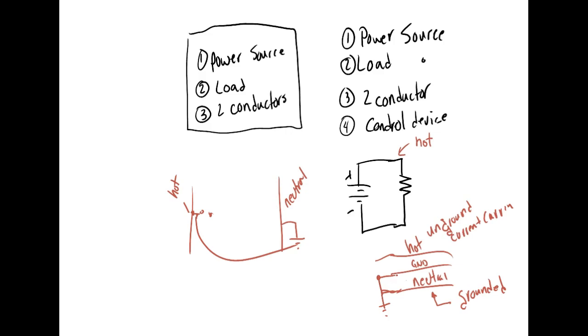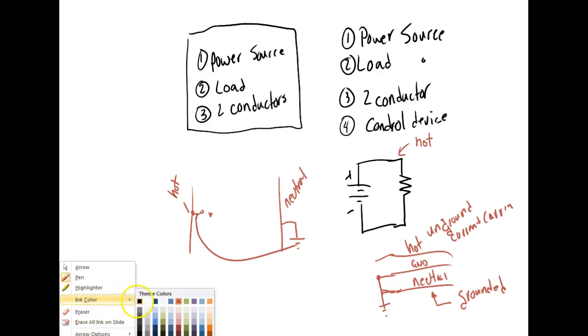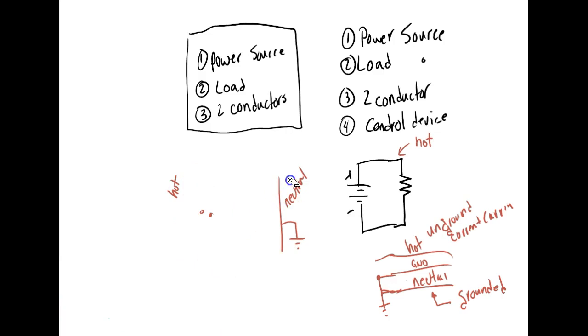Well, yeah, control devices can carry a load. In fact, a lot of control devices do. In motor controls, all your control devices carry a load, right? The current of the load is fed through the device. And this is also true on a solid state device. The current that runs a load has to go through the device, right? You understand? The problem is a lot of our solid state sensors have to be powered up, and this might be what's giving people problems.